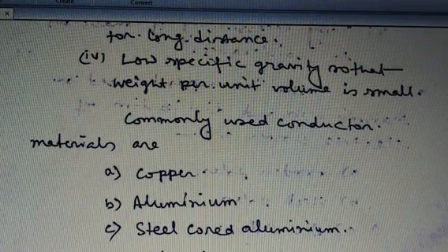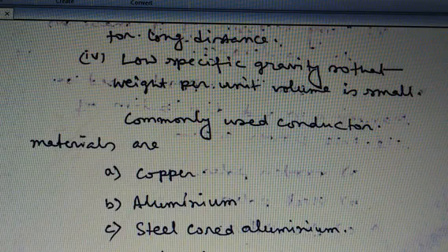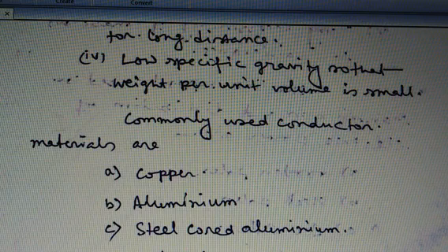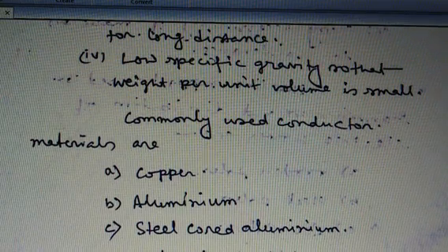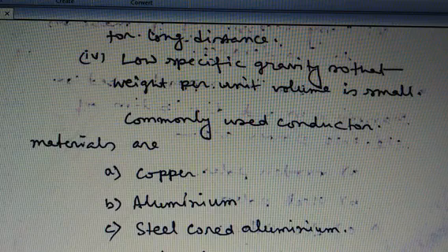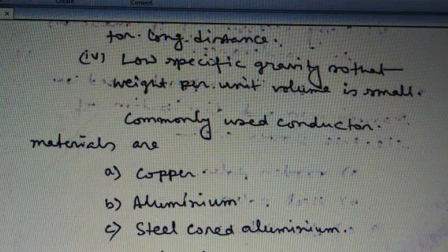Now, the last one is the cadmium copper. The conductor material now being employed in certain cases is copper alloy with cadmium. An addition of 1% or 2% cadmium to copper increases the tensile strength by about 50% and the conductivity is only reduced by 15% below that of pure copper.